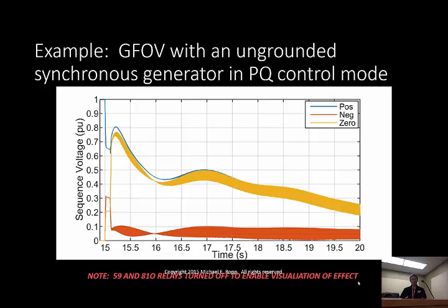And now you'll notice the generator is feeding the fault. What happens almost immediately is that zero sequence component jumps way up. It's basically equal to the positive sequence in this specific case because it's a bolted fault and a number of other situations. But this is our ground fault overvoltage situation. Now you'll notice, does it get to that ground fault overvoltage and stay there? No, it doesn't. It starts to fall off. Why? Well, this is the reaction of the governor trying to pull the thing back in because now there's a big load on the generator and the frequency's crashing.